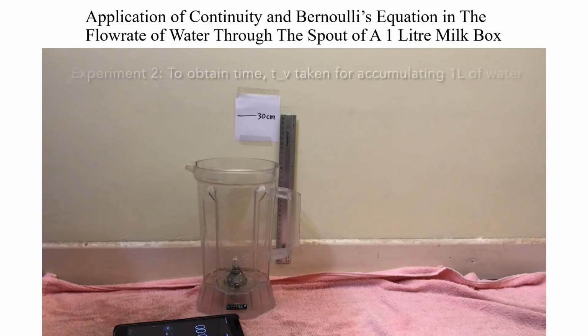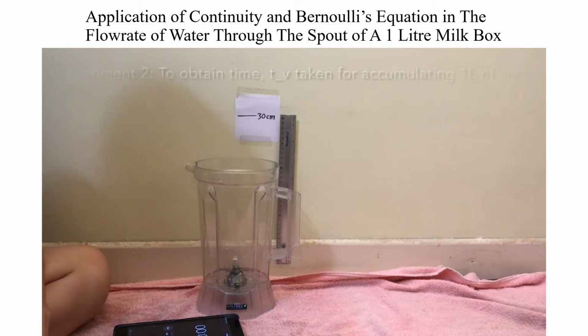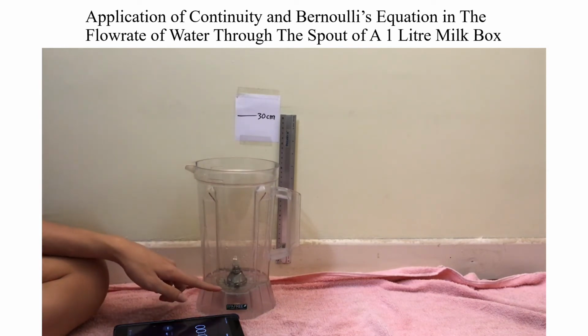In this experiment, we are going to find out the value of volumetric flow rate. So in order to find volumetric flow rate, we are going to obtain the time taken for the water to accumulate from 0 until 1 liter.